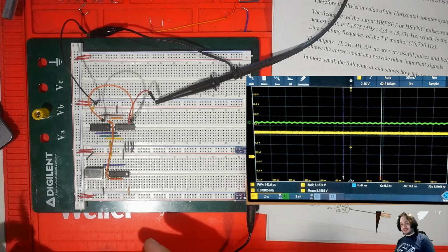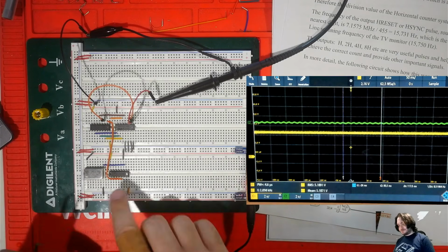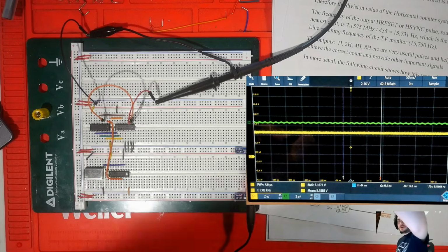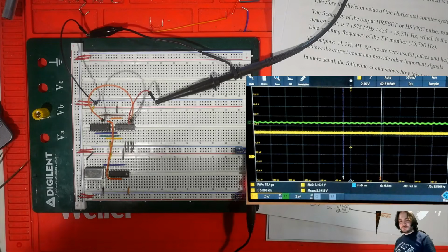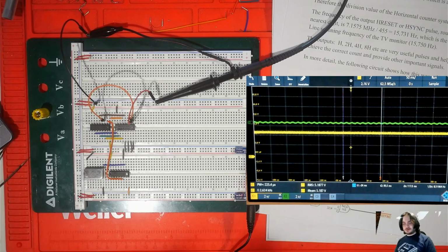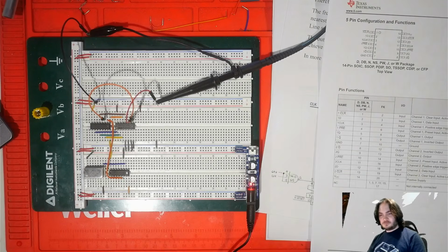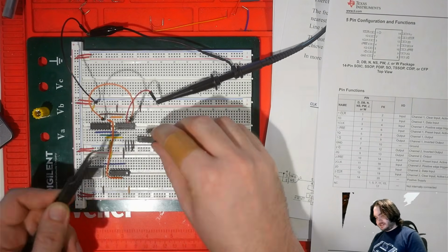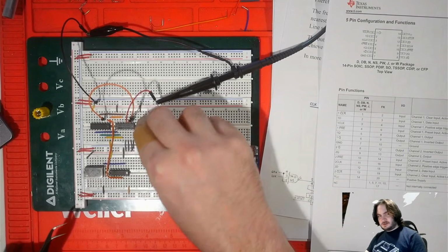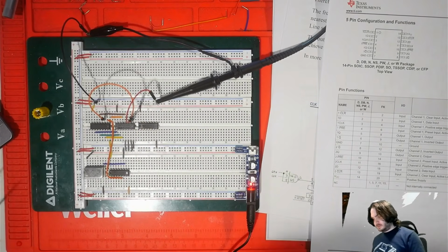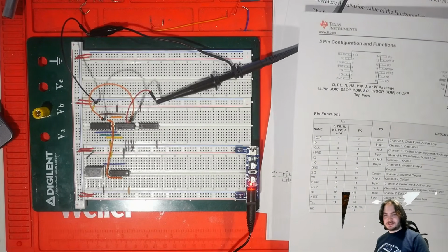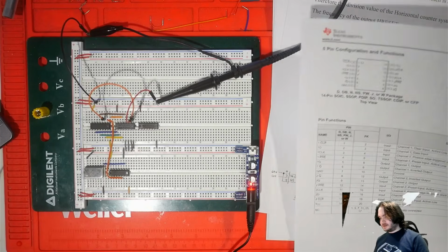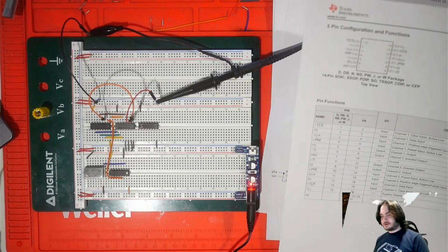It'll also help to extend this pulse a little bit, because what's going to happen is it's going to go like blip, and it's not going to be super useful for other parts of the circuit that we need later on. So next I'm going to add this chip. That's the 74HC74, and this is a pair of flip-flops. What that means is it stores a single bit of data to be used later.